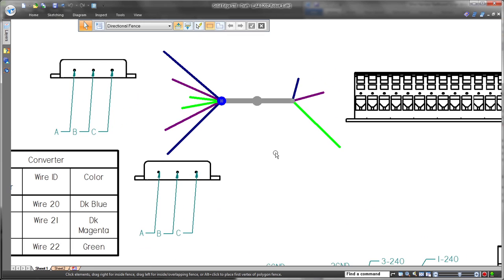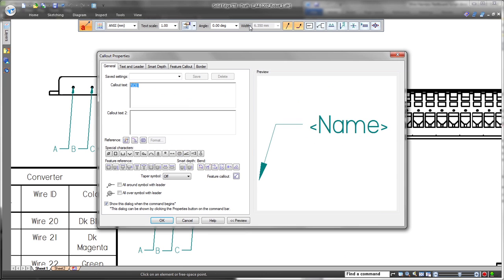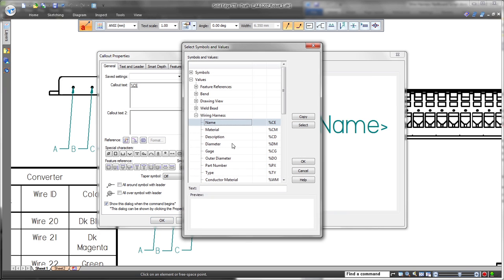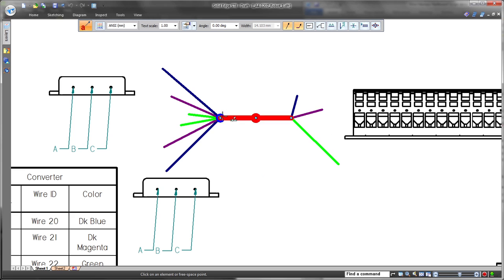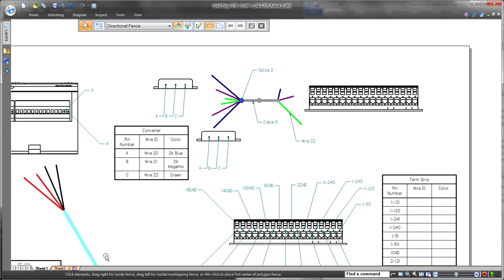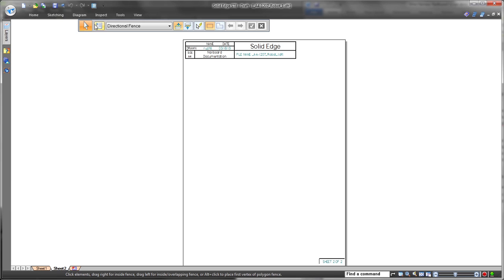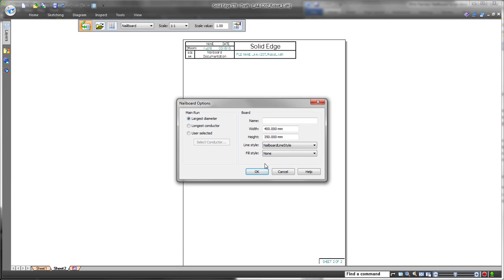Documentation of the harness's cables and bundles leverages Solid Edge's industry-leading drafting functionality. Here we'll finalize our electrical design by updating a nail board drawing. Solid Edge provides true nail board representations for layouts and connector tables. ST8 introduces splice representations on the nail boards. Watch as we place a callout to show the definition of the bundle and its corresponding splice.